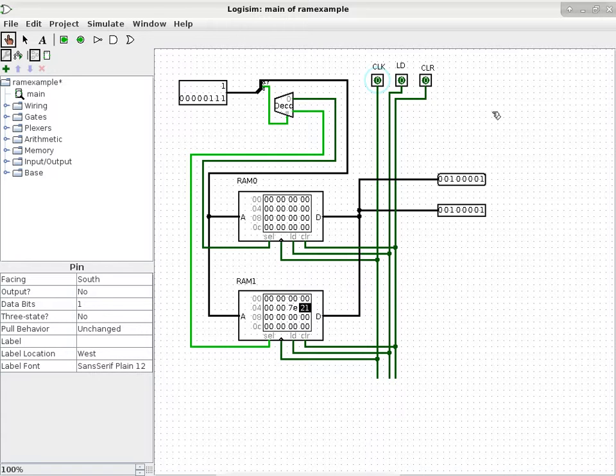With a burst mode operation, you only specify the address once. This is the start location. After that, every single time you clock, the RAM chip understands we're moving on to the next location. So you don't have to clock out the address bus every single time, and that saves time, okay?